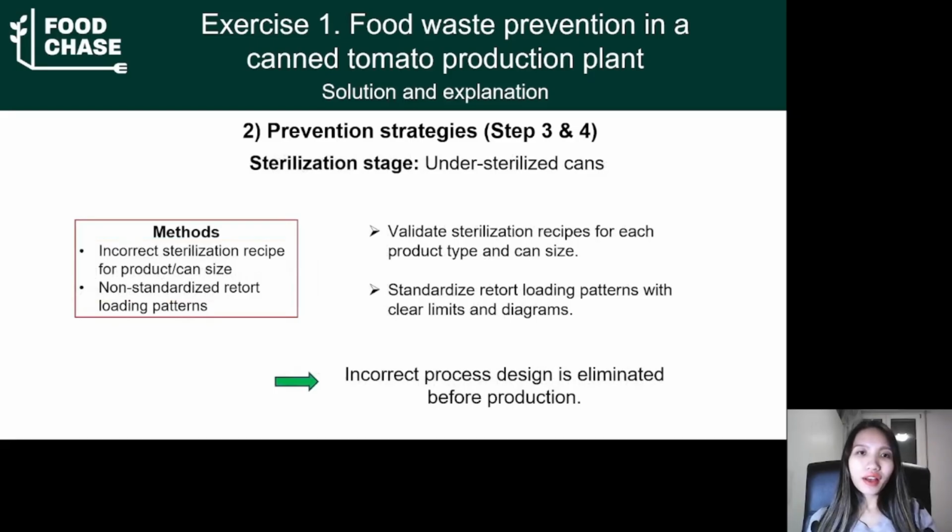Now we are going to analyze the solution for the sterilization stage. For the under-sterilized cans problem, considering the method category, we can apply validation of the sterilization recipe for each product type and can size, or standardize a retort loading pattern with clear limits and diagram. With this solution, incorrect process design is eliminated before production.